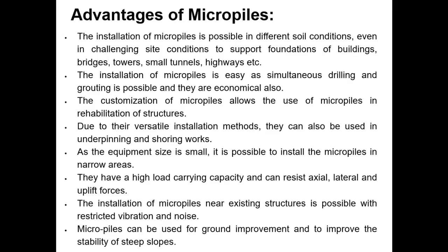Let's see the advantages of micropiles. The installation of micropiles is possible in different soil conditions, even in challenging site conditions, to support foundations of buildings, bridges, towers, small tunnels, highways, etc. The installation of micropiles is easy as simultaneous drilling and grouting is possible, and they are economical also.